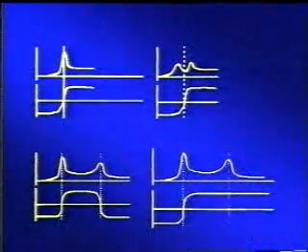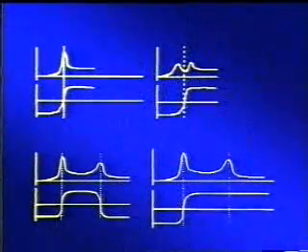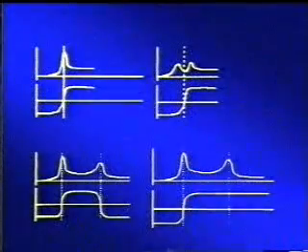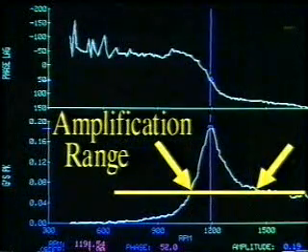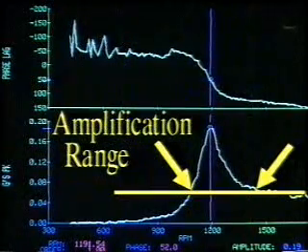These Bode plots can reveal good information about the machine conditions, especially the resonance frequencies and the amplification range. The amplification range is the frequency range where the vibration is amplified due to resonance.